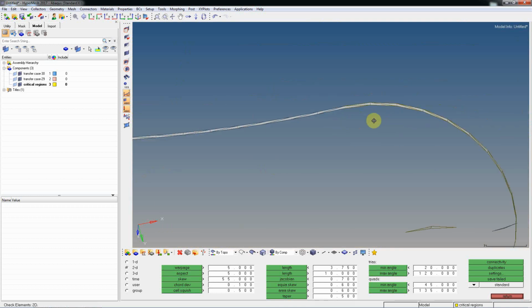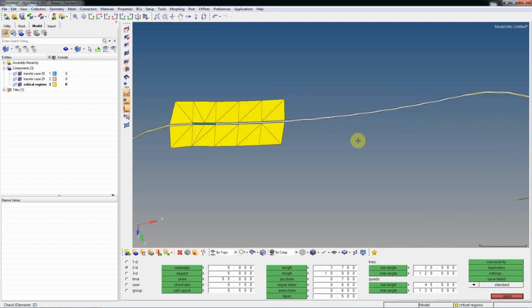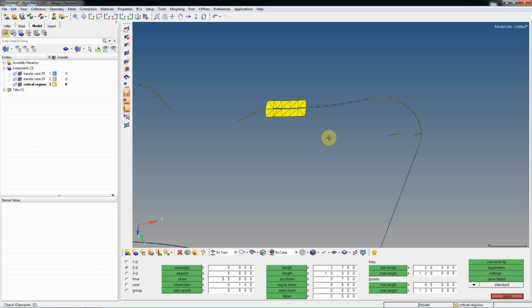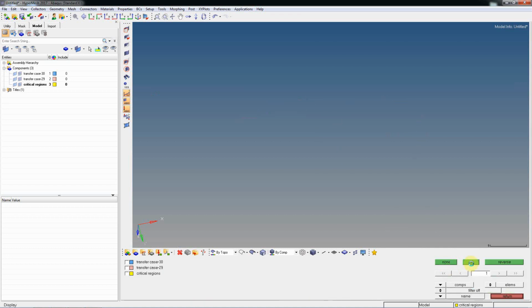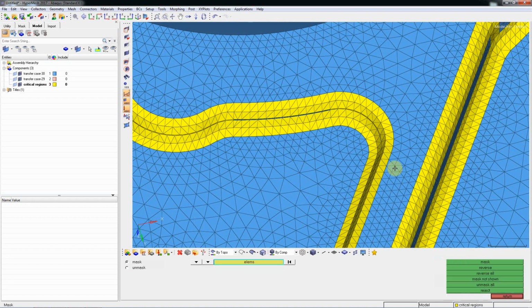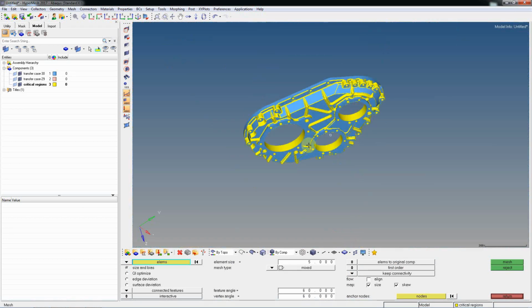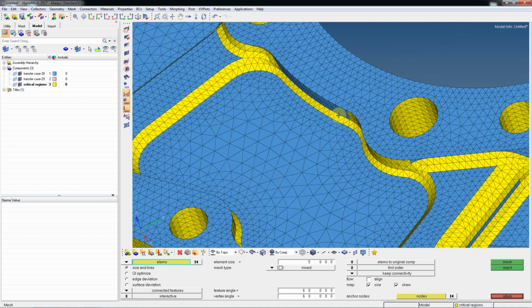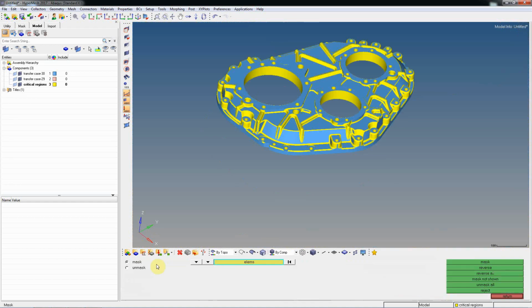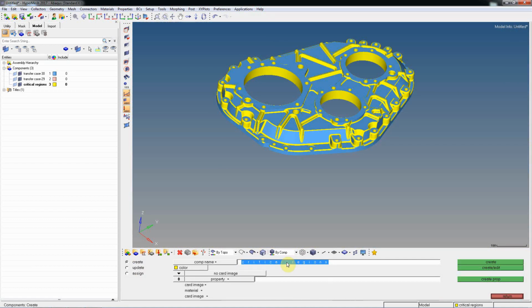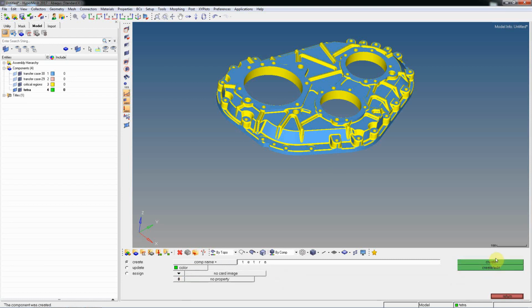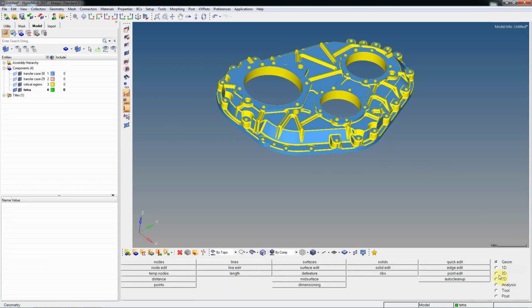Like this, you need to fix up the aspect ratio specifically while doing Tetra mesh, right? And maximum and minimum angle you can fix up by remeshing, right? So now what I'll do, I'll create a component as Tetra, right? So create, so Tetra component was generated.